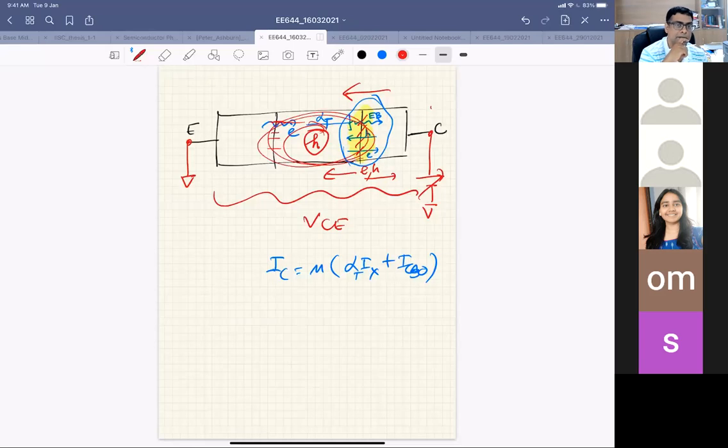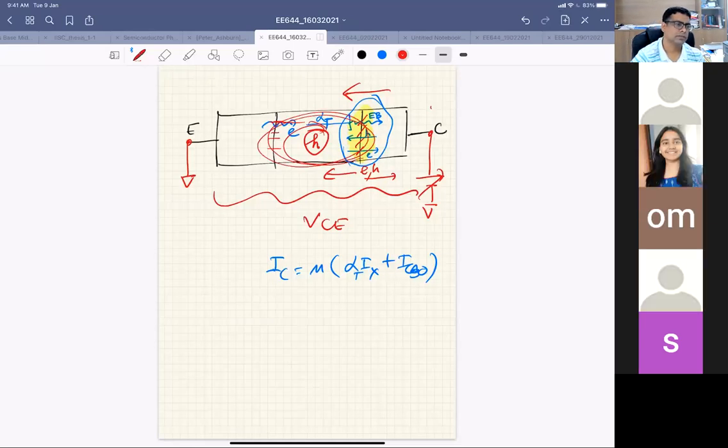Here we are starting with some small number of electrons being injected from emitter to base, but because of the positive feedback process it becomes very high with time. Here we are considering that because of hole accumulation, forward biasing of the EB junction is taking place.